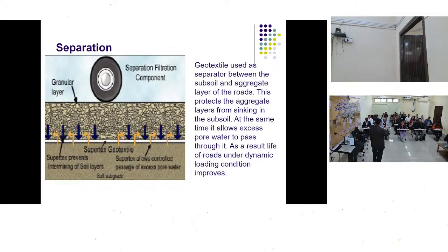So those loads are coming, and more of this granular material is settling into the soil particles, and this fine soil is getting pumped up, and the water is going out. And this is a continuous cyclic process happening because of rains. It's not that you get rain for one day and then you are going to have a dry spell for 15 days. So you have rainy seasons for maybe 2 months or 3 months or 4 months at a stretch. So this particular phenomenon occurs continuously.